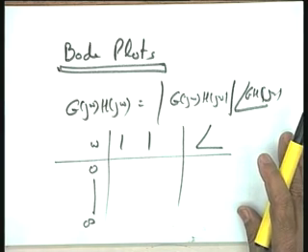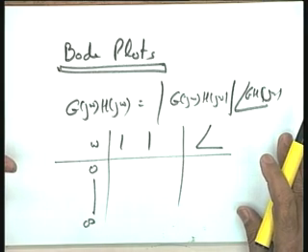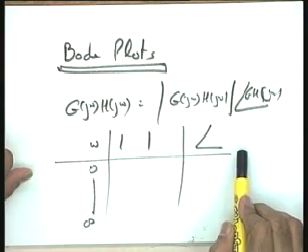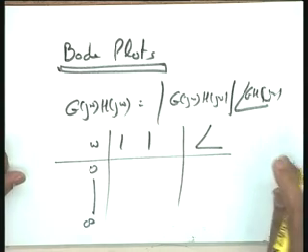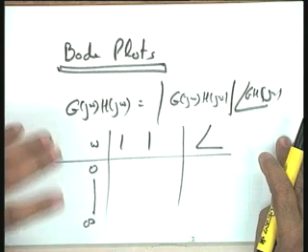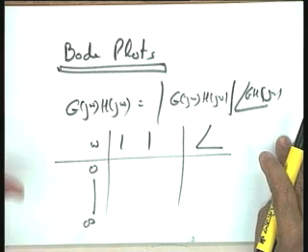Without any calculation, it will become a straight line asymptotic plot, and you will not require this calculation of omega, magnitude and phase angle, and all your conclusions about the system stability, the gain margin and the phase margin will be easily interpreted on the Bode plots.